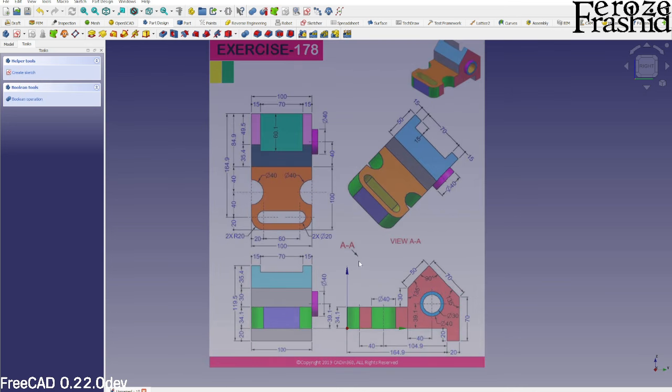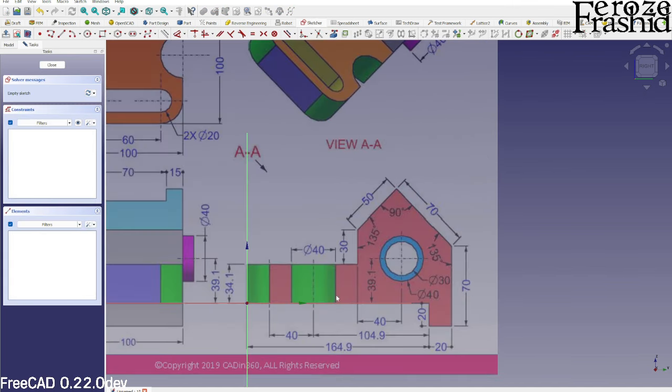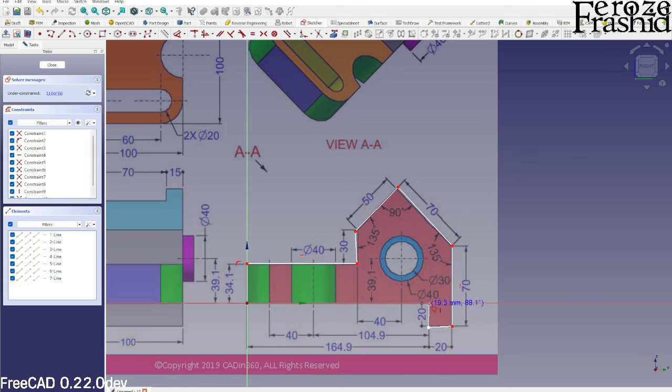And I wanted to get a head start on these new features. All right, so in Part Design, get a sketch on the YZ plane, and quickly I want to draw the outline using the polyline. It will be quick sketching, and I can come back to fix these lines here and there. Right now, I'm going to make this one vertical.